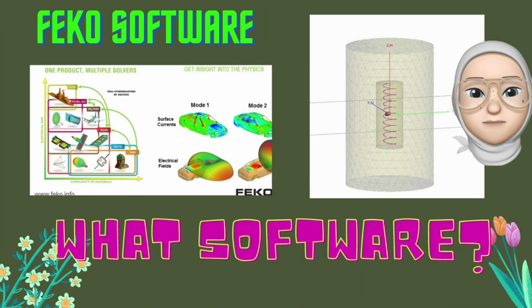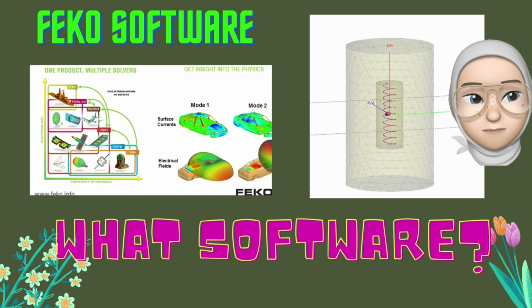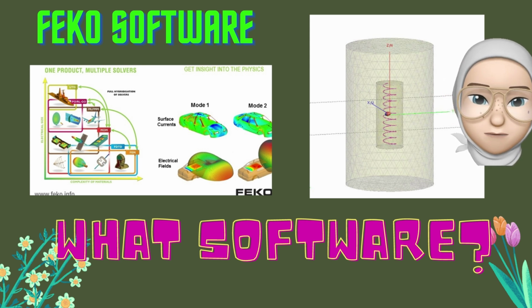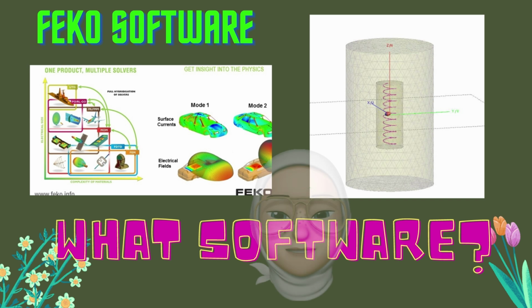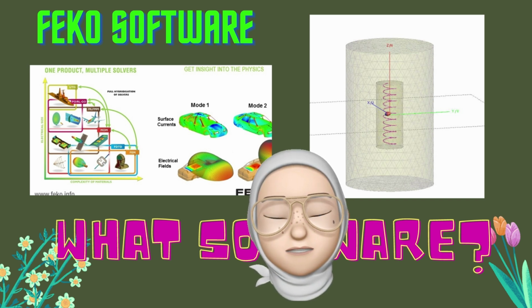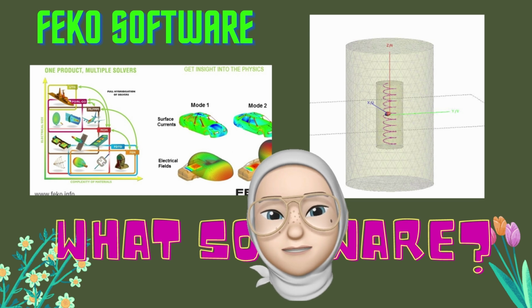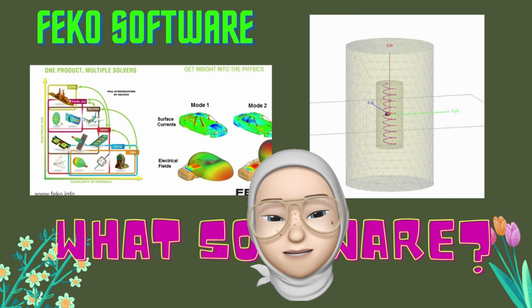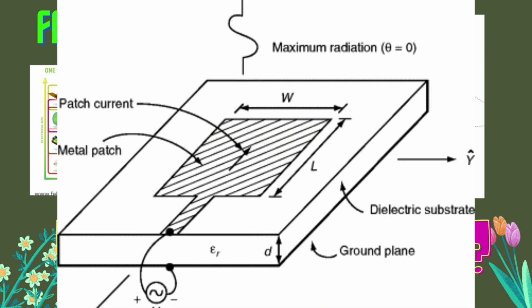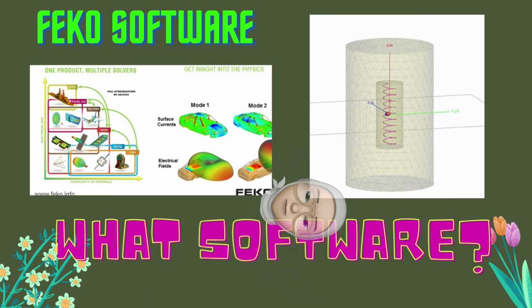In this research study, the electromagnetic (EM) simulation software that will be used is FEKO. FEKO is a computational EM software for 3D EM simulation developed by Altair Engineering. FEKO uses the method of moments (MoM) integral formulation of Maxwell's equations as a solving scheme, which subdivides the wire and the material components into smaller segments through meshing. FEKO is suitable for analysis of various kinds of antennas, for instance horn and aperture antennas, strip antennas, array antennas, helical antennas, and so on.